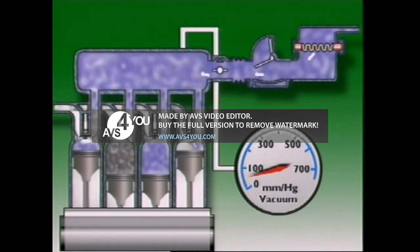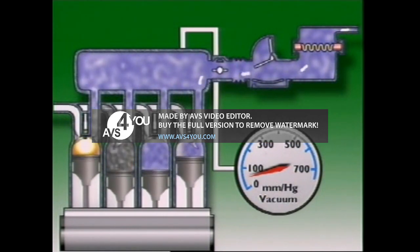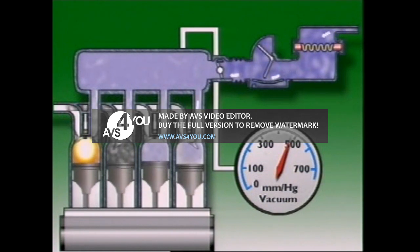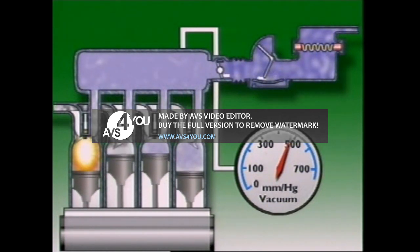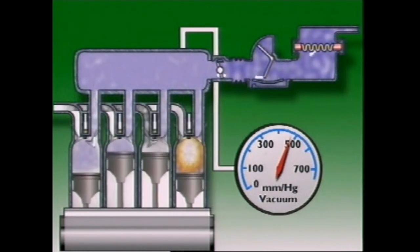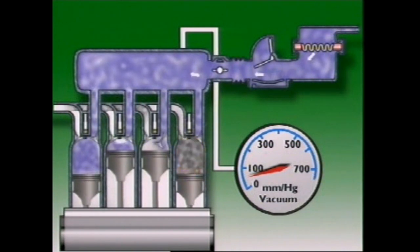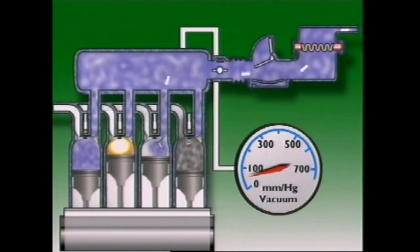When the pistons draw air away from the manifold more quickly than air can pass the throttle plate into it, the pressure in the manifold falls. At idle speeds, this pressure is low. A high depression or a vacuum exists. As the throttle plate opens, the pressure approaches that of the atmosphere. The depression or vacuum tends to fall in value.